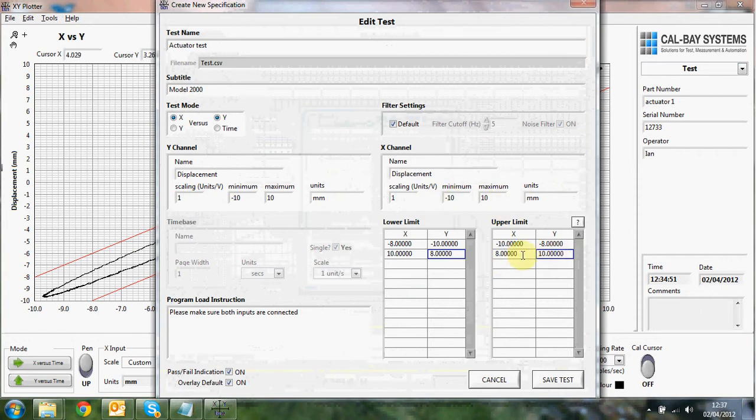So whatever you set up as your scaled units up in this section here, these are the values you'll be seeing. So once the system is set up and you've got scaled numbers, then you just basically put your upper and lower limits as two sections in here. You can have multiple sets of lower and upper limits, so you can have very complex masks if you're doing sort of hysteresis type of analysis, but you can set those up however you like.